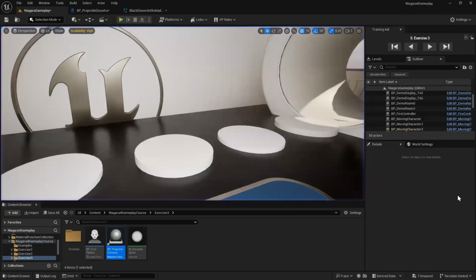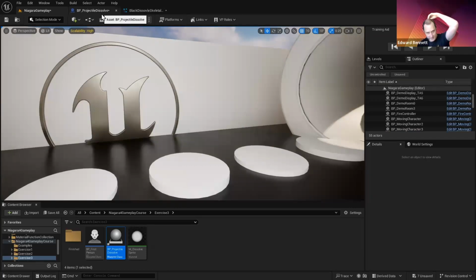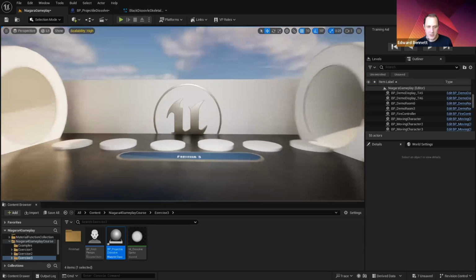Scaling particle systems can be tricky because you can scale the system, but the particles have already spawned with their own kind of world space value. So if you're not using local space, scaling the particle system directly from there is always going to be a little bit tricky. Right. Okay, that's interesting. So that's why the scale is kind of not directly working. It's not very intuitive, but that's just a heads up for people. Yeah, no, that's good. I realize I go on for hours just making it smaller and smaller and smaller. Right. Okay. So I think that's sort of a logical point to think.